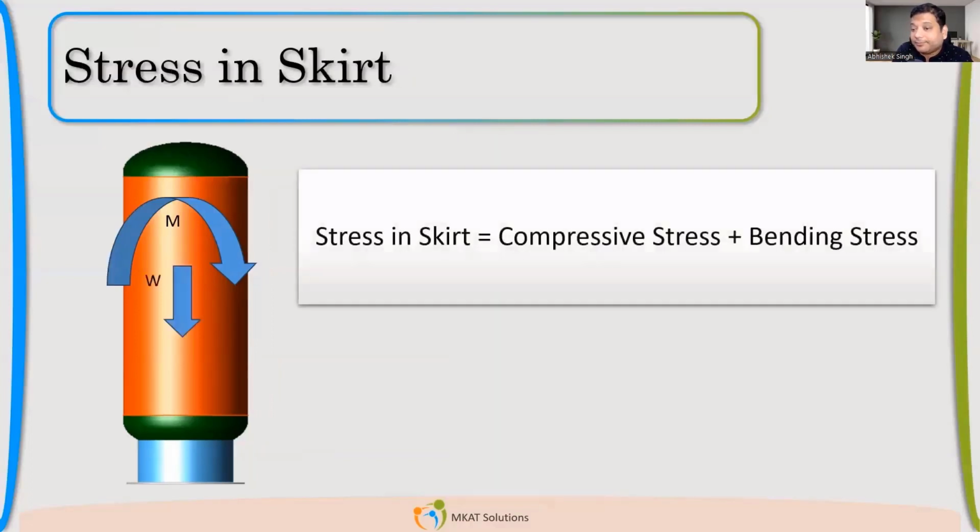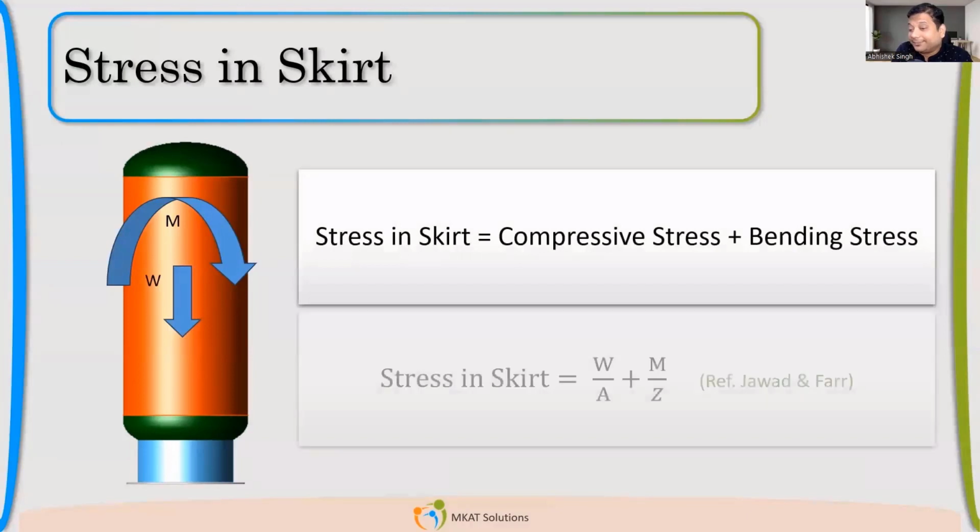Okay, now it's time to combine. So stresses in the skirt will be this. Now for both the different sides, you need to do the different additions and compression. So you have to find the tension stress and also the compression. If you see in PVElite also, you'll get both the columns calculated. In tension, how much stress is there? In compression, how much stress is there?